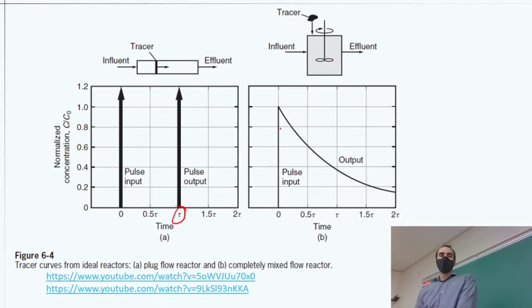And so you're going to have your initial measurement be whatever that dilution created. And from there, it's just going to be slowly decreasing as you still have clean water coming in. So you have that clean water in the influent, and you're measuring what's coming out. Turns out that since it's completely mixed, you could be measuring what's coming out, or you could measure what's inside, and it's the same thing.